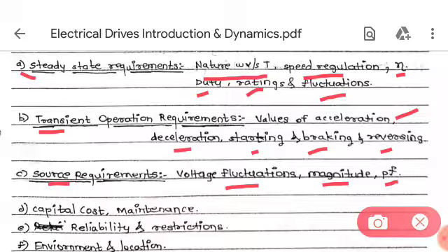If the power factor is poor, the reactive power requirement is high, and reactive power is the power which is getting stored in the different circuit elements, inductors and capacitors. It is just getting stored, it is not doing any useful work. Useful work is done only by active power. Reactive power is getting stored in the line capacitance, any stray capacitance, or any line inductance at high frequencies. So reactive power has to be reduced.